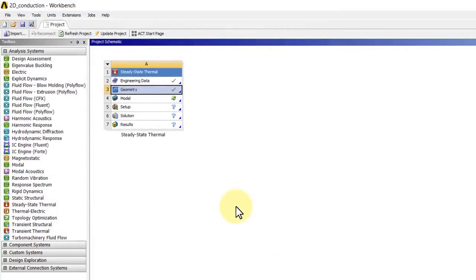And so that's a couple of ways in which you can save the project, and you have to be a little bit careful. I've seen students saving things to a flash drive and then running ANSYS from a flash drive or a USB drive, and that tends to be very slow. So what I would recommend is that you move things to a local drive, say the desktop, you run things from the desktop, and then once you are done, exit ANSYS, and then you can drag things onto and save things onto your USB drive.